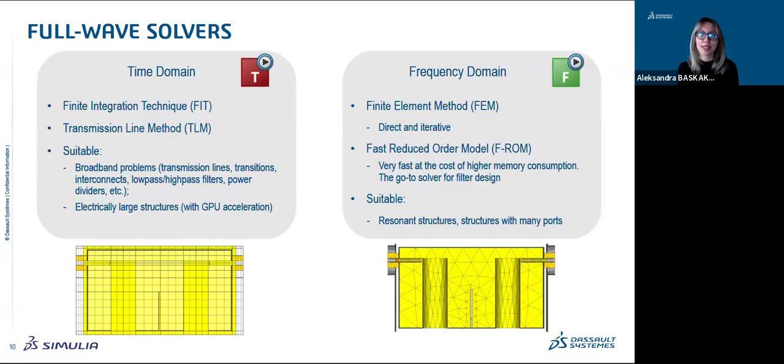In order to simulate passive components, the full wave solvers based on time and frequency domains are the most appropriate for the task. These solvers are founded on different numerical methods. The time domain solver is based on the finite integration technique. By the way, this technique was developed by Professor Thomas Weiland, who is a founder of CST, and the solver is our flagship solver, and it is very well suited for devices that have a broad bandwidth, and it is based on hexahedral mesh type.